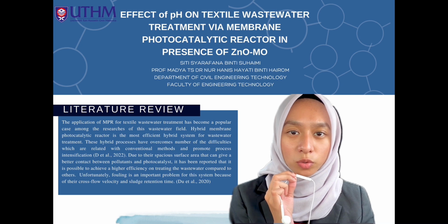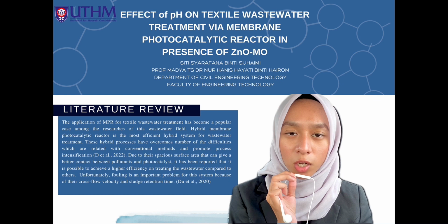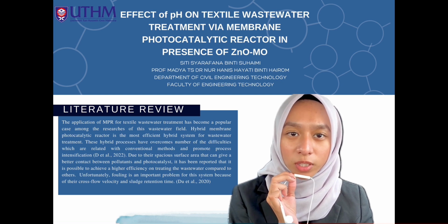It is due to their spacious surface area that can give better contact between pollutants and photocatalysts. It has been reported that it is possible to achieve higher efficiency in treating wastewater compared to the others. Unfortunately, fouling is an important problem for the system because of cross-flow velocity and sludge retention time.